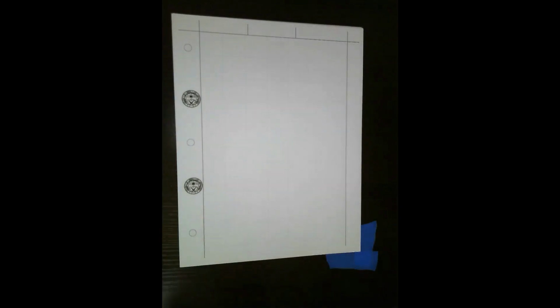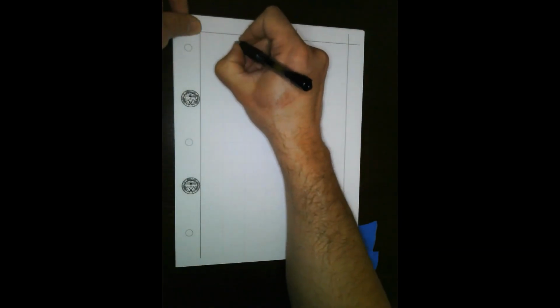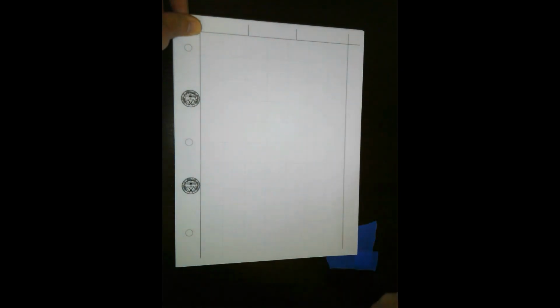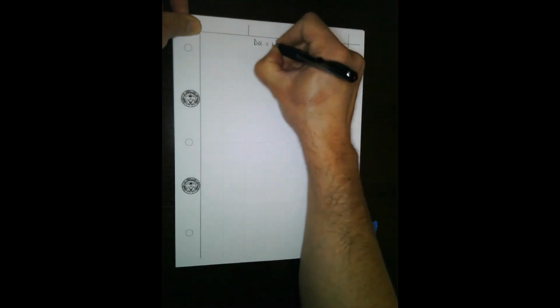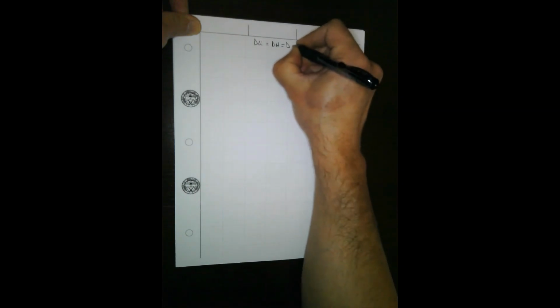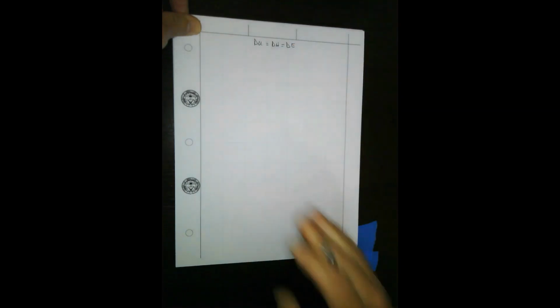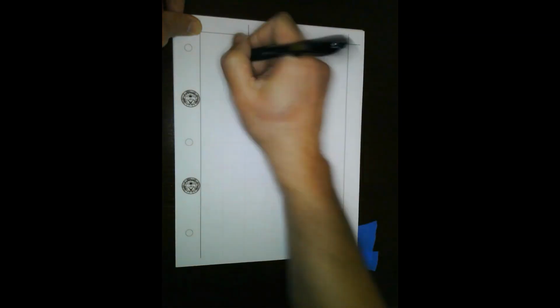All right, so we're looking at our scrap iron in an electric arc furnace. One thing we want to point out is we're assuming pressure and volume aren't changing while we're melting our scrap. We have an electric arc furnace, and so delta U equals delta H, and that equals our total change in energy. Okay, so enthalpy is pretty much the only change. So we're putting in electrical energy.